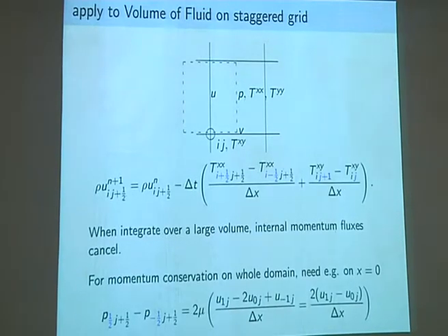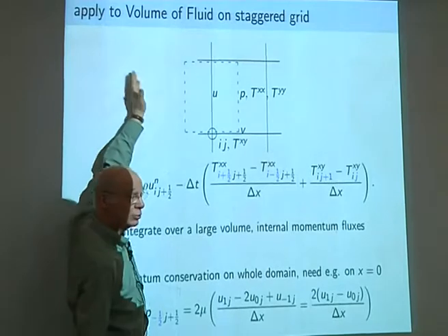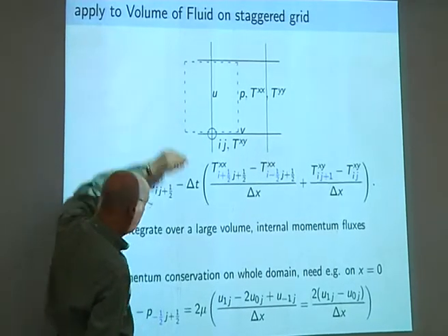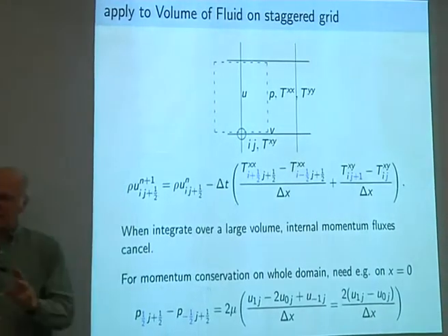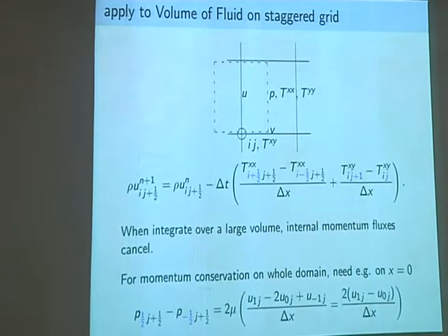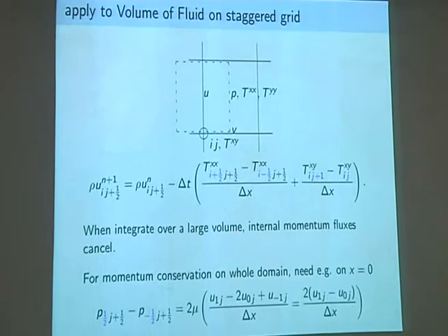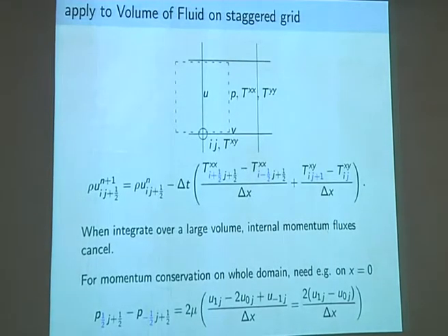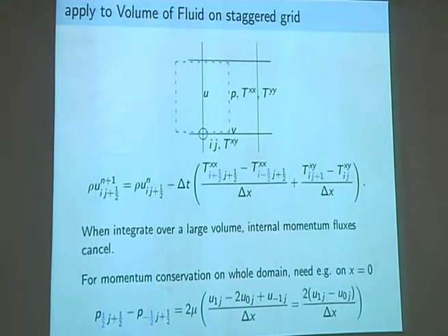And to deal with the final half block from the internal point onto the boundary, you see we've only gone halfway towards the next point in the boundary. You need to have a boundary condition that tells you about what the stress Txx is at the ghost point outside the domain. And that turns out to be effectively telling you what the pressure is at a point half point outside. So you have to get the pressure correct on the ghost point outside, and then we work the pressure on the boundary as being the average of half a point in and half a point outside. These staggered grids are complicated.